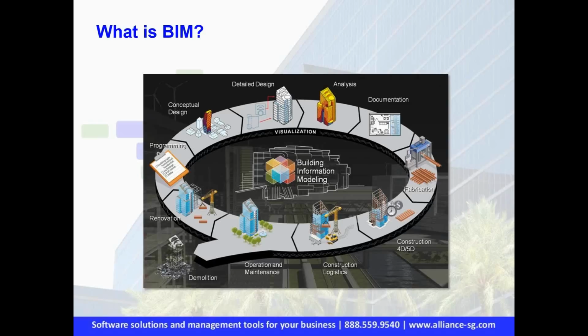Navisworks is a tool that allows you to do a lot of conflict resolution, saving a lot on the RFI process. As that goes into Revit, Navisworks allows you to take, let's say, the mechanical, plumbing, electrical, maybe your drywall, and see where you may have some conflicts and interferences that you can delve into and flush out before it even hits the field.